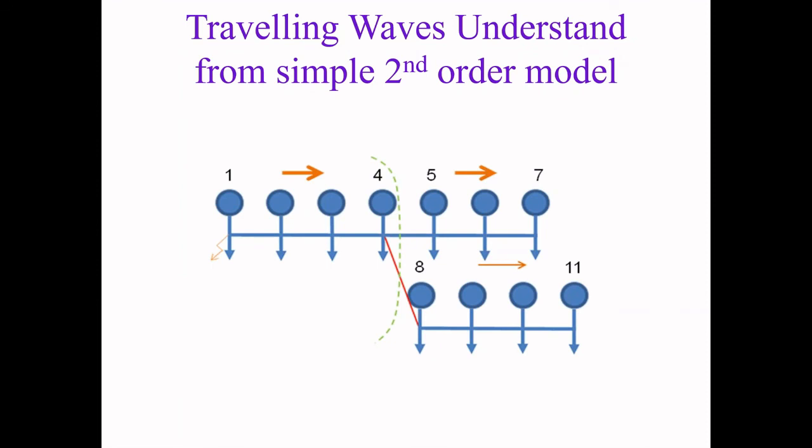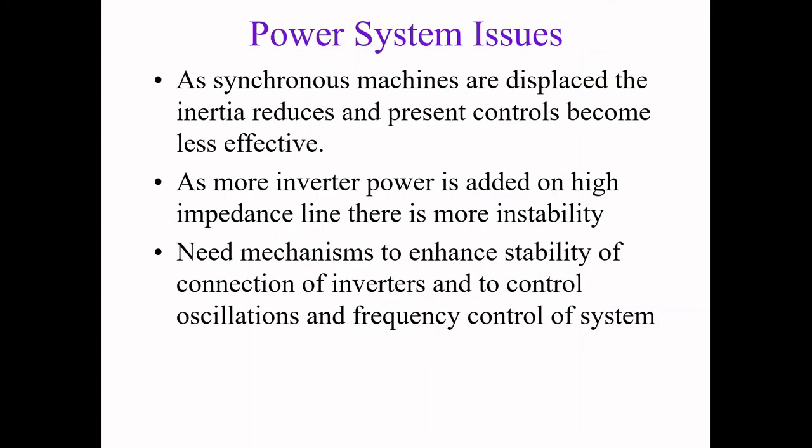An example that I like here is when we were starting to work on traveling waves on groups of synchronous machines. What tends to happen is that there is a process whereby if a fault happens, say, in the top of Queensland, it gradually propagates and influences synchronous machines elsewhere. But to get an understanding that this is really a travelling wave problem, we can represent each one of our generators as a simple second order model. Is that the perfect model for the process? No. Does it give you a handle on what's happening? Absolutely.